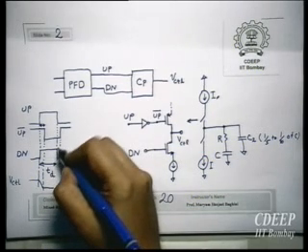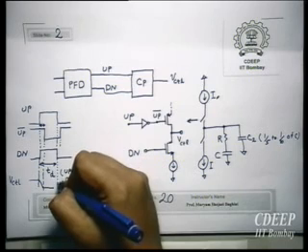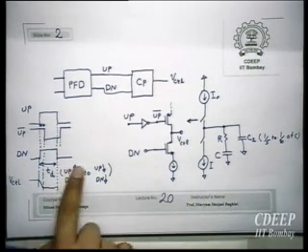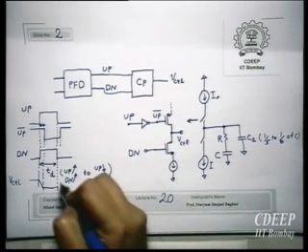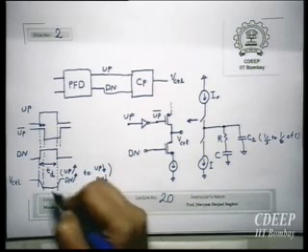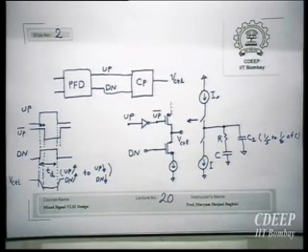Now again here, at this point, when up bar is low and down goes low, I have a source current, which returns the voltage back to the original value, considering the two current sources are exactly the same. Now see, this appears as a ripple on the control voltage. Though we are sinking and sourcing some current, for this duration there is a ripple.